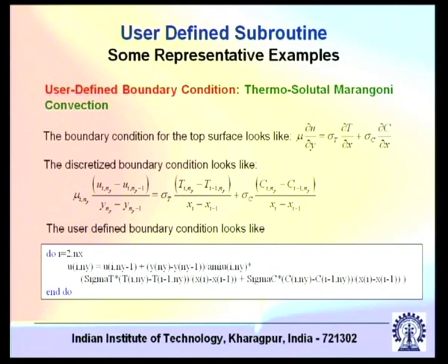Okay. So this is mu du/dy for the viscous shear, and the shear due to surface tension you can write, for example, as del sigma del x. Del sigma del x is del sigma del T into del T del x, where sigma is the surface tension coefficient. So del sigma del x is a shear stress because of the gradient of surface tension. Y is, for example, the direction normal to the interface, and x is the direction tangential to the interface, that is the nomenclature we are considering.